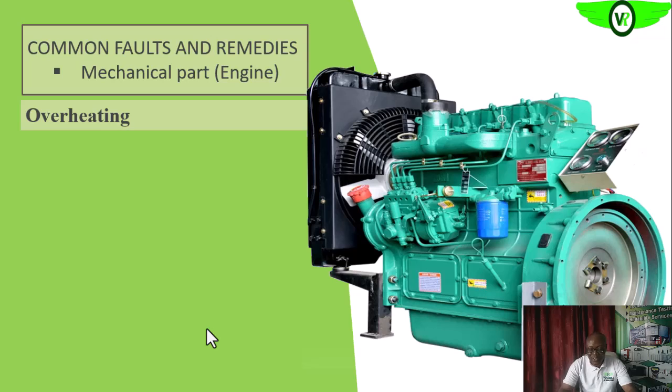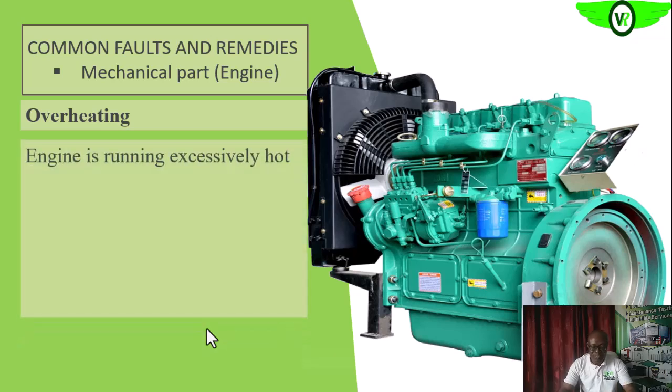So overheating is another common problem with diesel engines. Overheating, so that is generating excessive heat, more than what is normal. Okay, so what could be the possible cause? Low level of coolant.